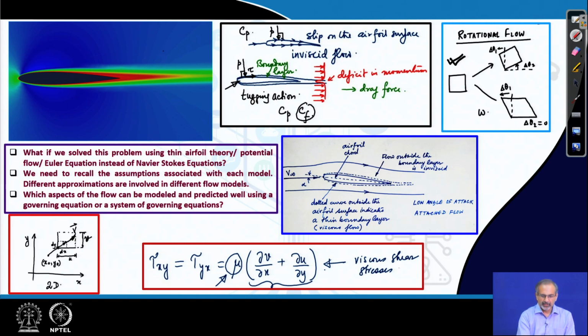And therefore, the region which is in non-blue, typically if you are talking about colors, those are the regions where the rotational effects will be stronger, and that too the reddish region seems to be the most rotationally affected region. One may say that if you are in the blue region, perhaps you can think about the flow to be an inviscid kind, which is not a very bad approximation really.